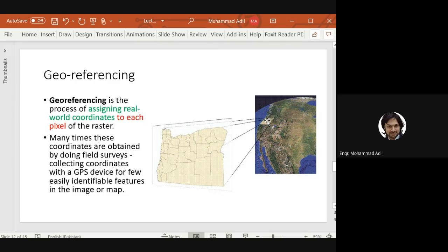So what we do is we know that now we have systems of WGS 84 or EPSG 4326 that represents coordinates on planet Earth. So if to any point on this map we assign those coordinates on planet Earth from latitude, longitude, from your GPS or anything, then from that we can measure distances anywhere using a scale drawn on this map as well.